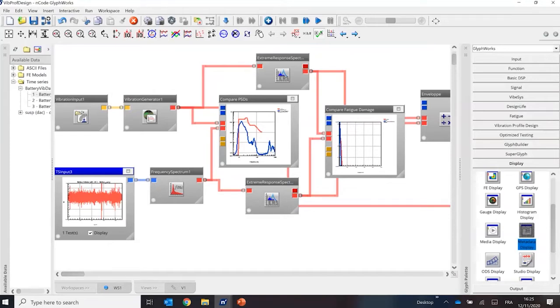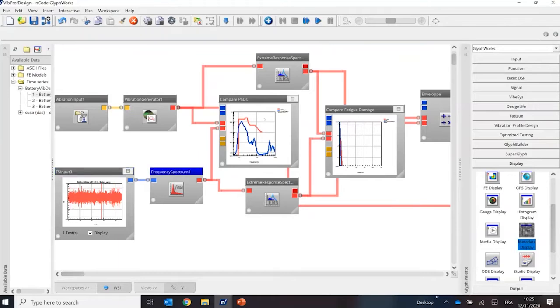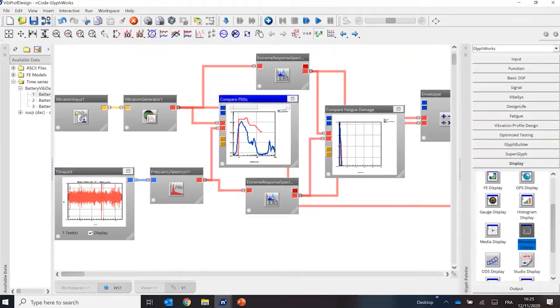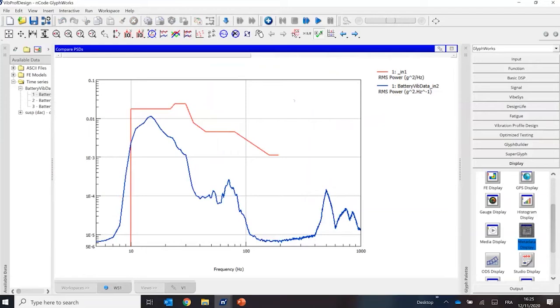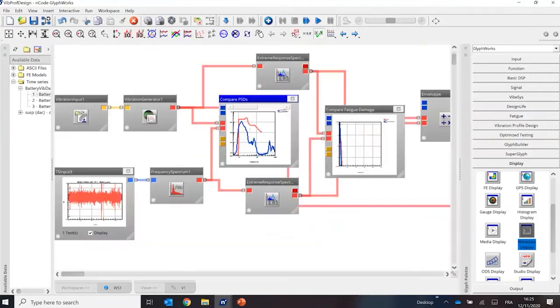In this example, let's say it's a concatenation of a few events here, and I'm taking the PSD of that signal, and here I'm comparing the PSDs. Are they really comparable directly like that? I'm not sure. The red one, which is coming from the standard, is meant to last, I think, 3 hours, whereas this is the PSD of a few 100-second signals. It's not directly comparable. You should compare something that's in the same domain, right?